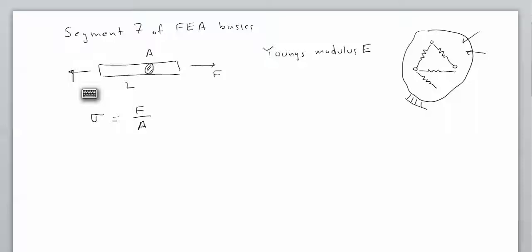But remember that the stress at a point is actually made of 6 components, 3 components of normal stress and 3 components of shear stress. When I write something like that, implicitly I'm saying that all the other 5 stresses are much smaller compared to this axial stress, and therefore they are being ignored.